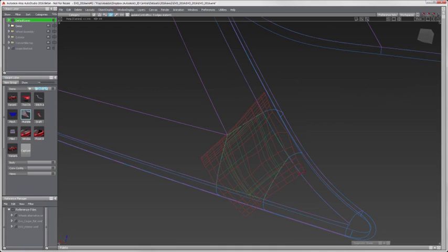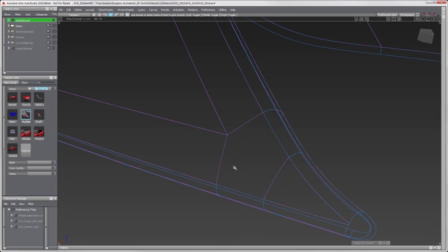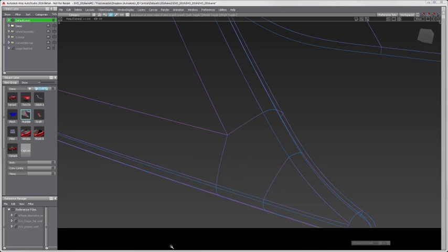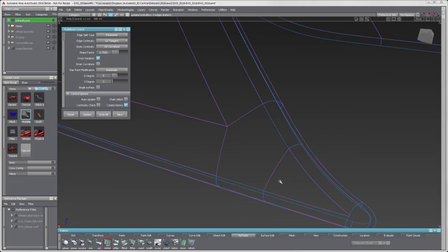This is the output of last year's n-sided tool. The replacement tool for 2016 is the Multiblend tool. Use this tool to fill in closed gaps which have 3 or more edges. This tool should not be considered a Class A surfacing tool, but provides a great way to build a nice-looking, hard-to-build surface quickly.